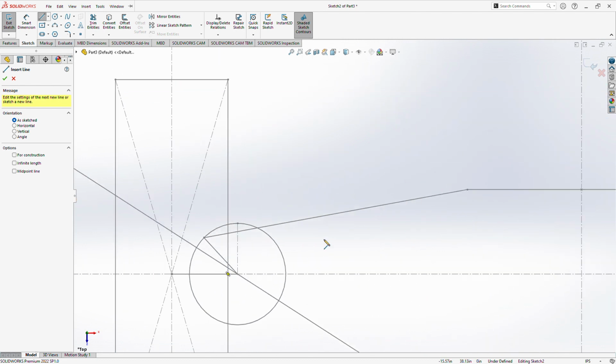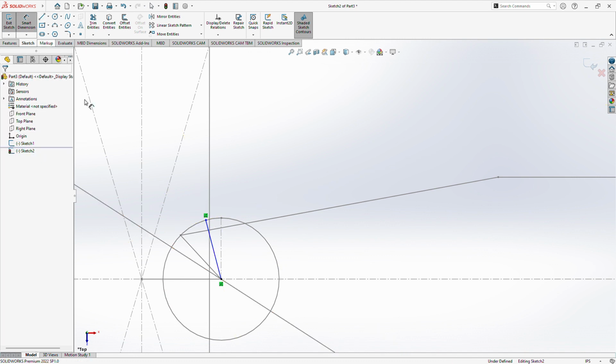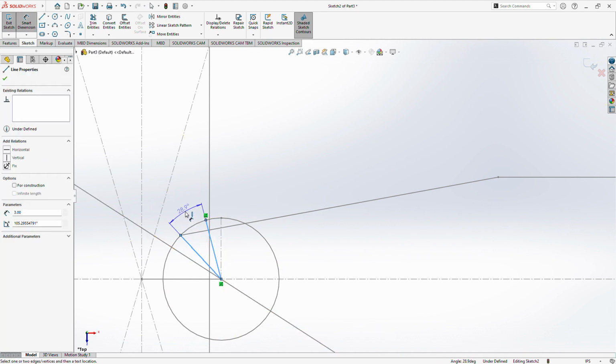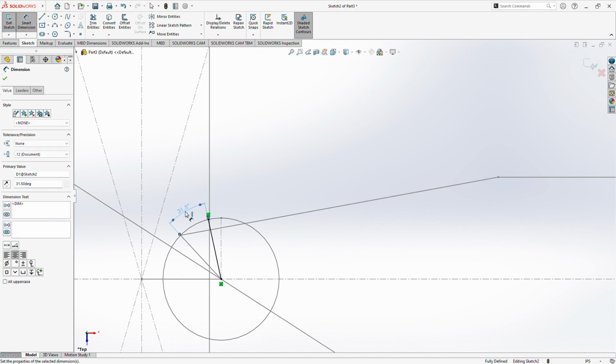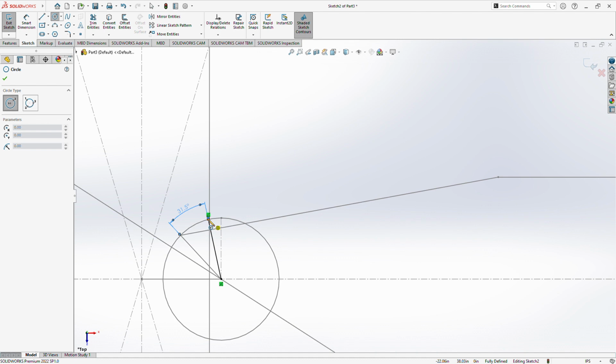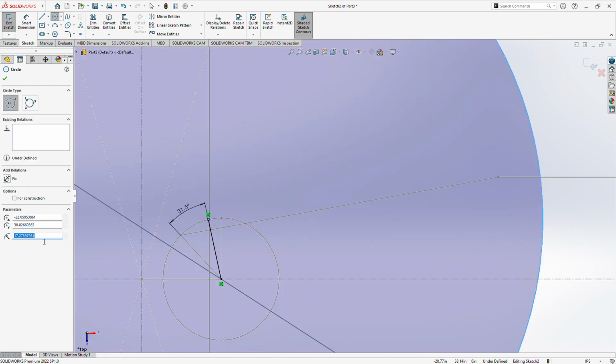Okay, the whole arrangement will move in the locus. Okay, we'll take a point here, we'll mark the steering radius, take the angle as 31.5 degrees. The inner turning and outer turning angle is 31.5 degrees. From this point, make a circle whose radius will be equal to the tie rod length, the length of the tie rod which we got from here.